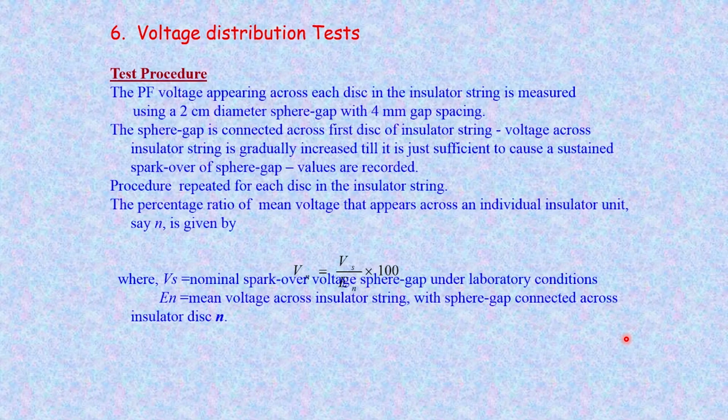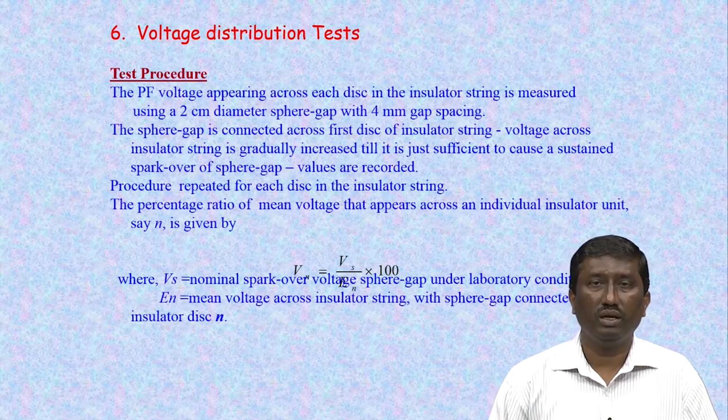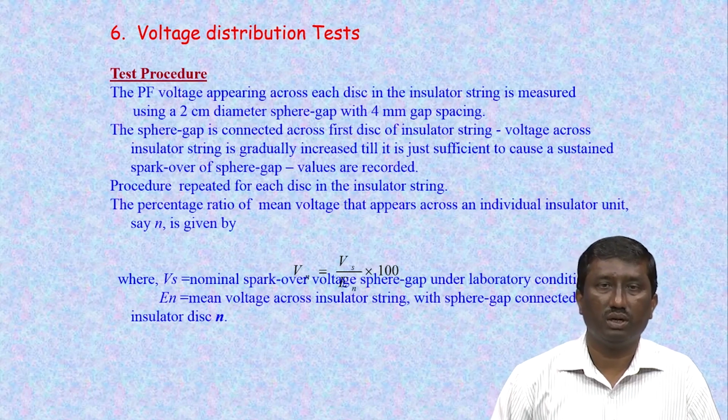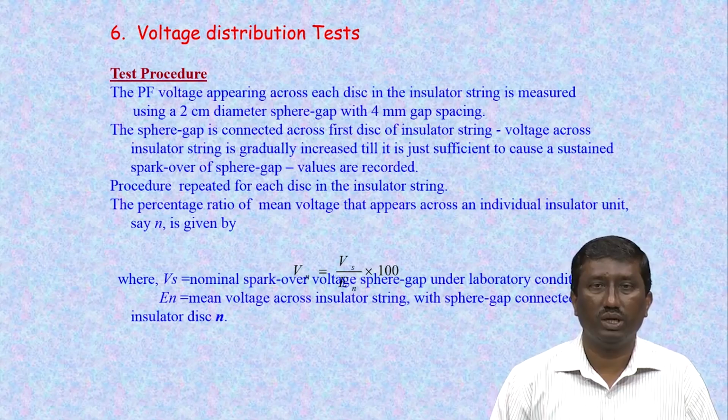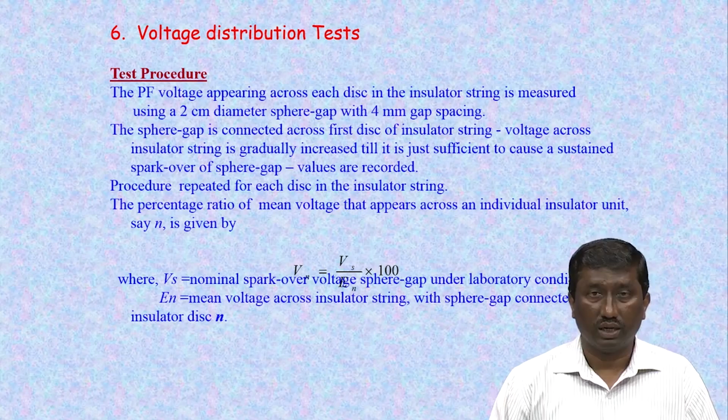Next to radio interference measurement, another important test which has to be carried out for reliability is on the insulator string, which has to see a proper potential distribution, or voltage distribution, across each of the insulator units. The main purpose of this voltage distribution test depends on the voltage level. As mentioned earlier, for 220 kV and above, voltage distribution tests are made mandatory in the country.